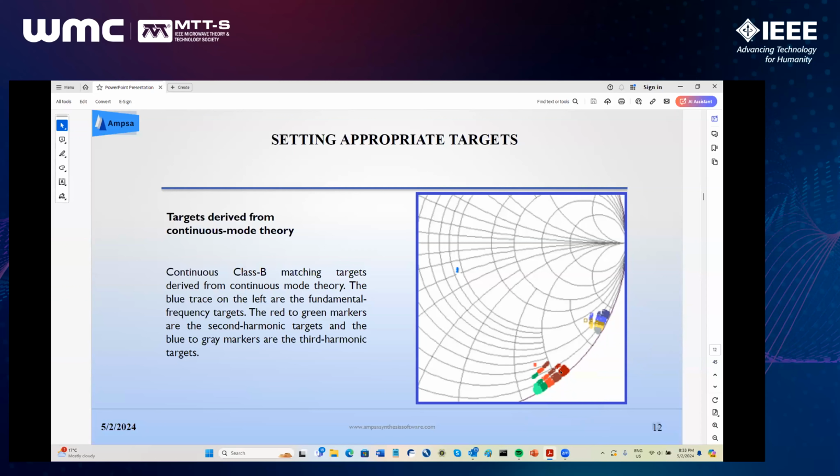Now, these are interesting. The red is low frequency and the green is high frequency. So these go clockwise. Now that was done by cheating a bit. Oh, I'm not cheating. It takes long to explain, but basically, normally these will go anti-clockwise. But you can make them go clockwise, but I'm not going to talk about it at the moment. This is the third harmonic. So you can see you will have to go around the Smith chart for the second harmonic, and then quite around again to get here to get a third. So this will not be quite so easy, but you can do it.